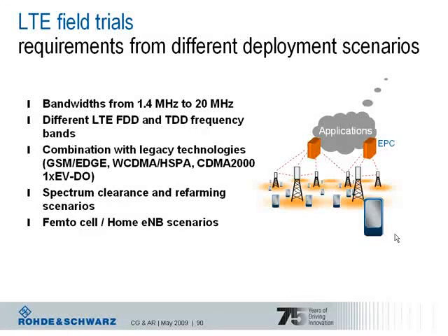So you need to make sure before you start and deploy the LTE, what is the situation in that spectrum? Is it really available for LTE already? What are the interference situations there? In future also we will see more femtocell scenarios in LTE, that's the home eNode B, home base station. These will be deployed on a large scale, so also from that we would expect more requirements for trials and LTE specific requirements for the home eNode B.